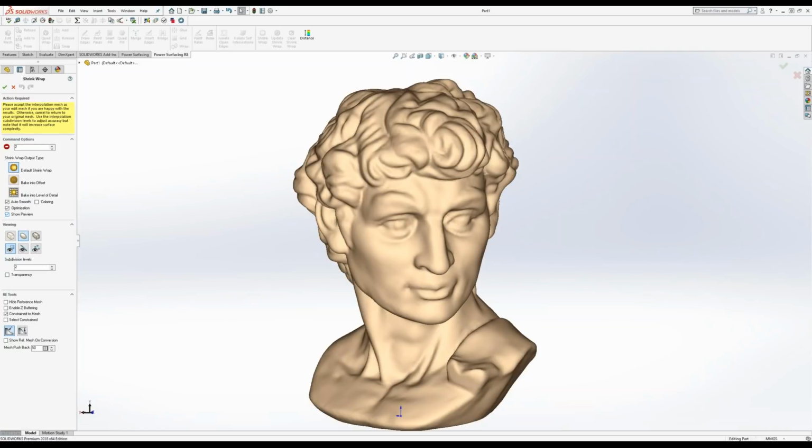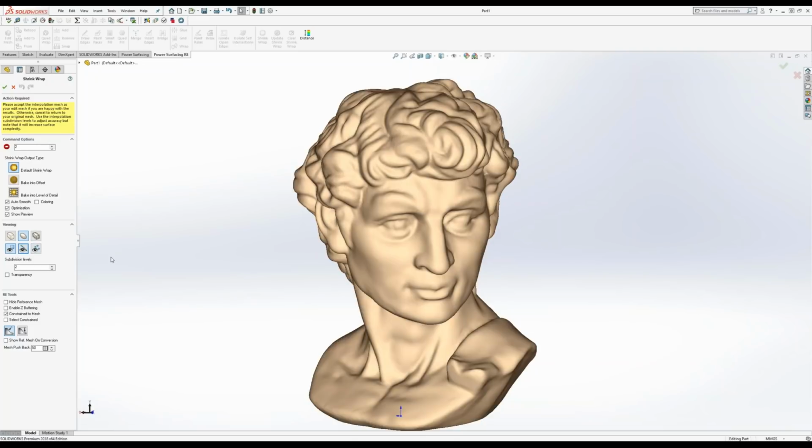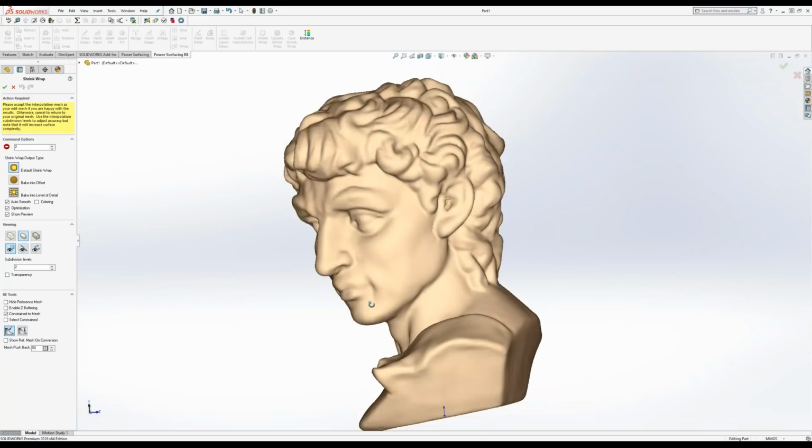There you go. So now, what we've done is we haven't actually increased the mesh density. So we have the same mesh, but I have added detail underneath the hood, so to speak. In other systems where you're doing this sort of thing, you'd have to go finer and finer and finer to pick up all of that detail. But that's not the case with what we're doing here. We can pick up that detail and sort of embed it so that we can still have a fairly lightweight mesh that we're dealing with.